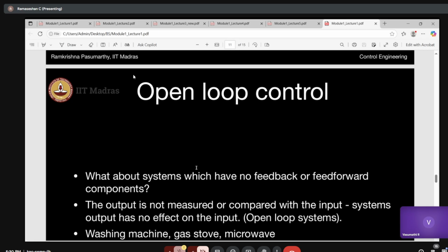So what is your main objective? Like, we should focus on controlling how much time? Is timing our main constraint? What I'm saying is, if your control gain is too high, the system will respond fast. But if the actuator is fluctuating quickly and the time constant of the system is not in that range, then it will become unstable rather than stable. It will oscillate very much. Okay, sir. Okay.